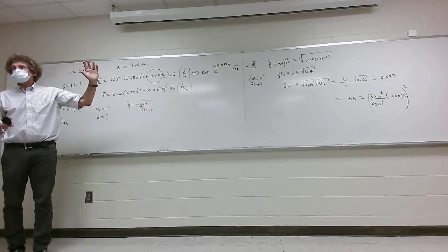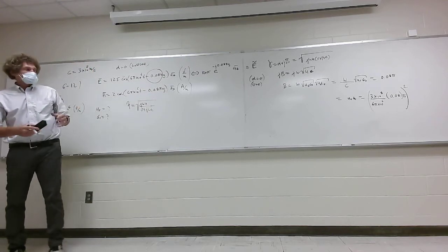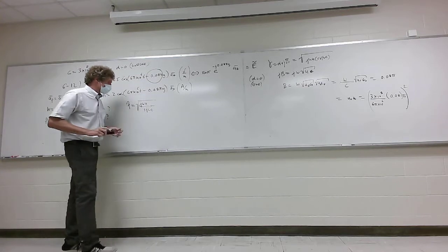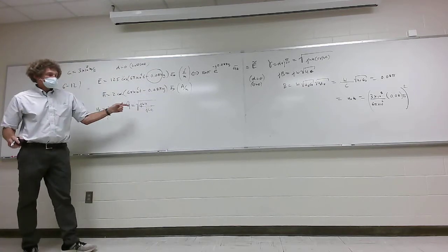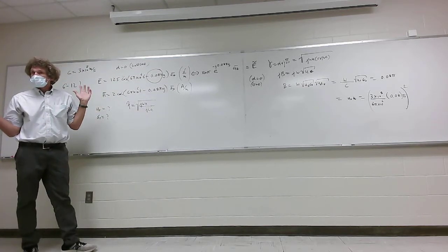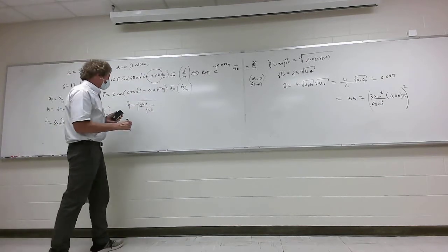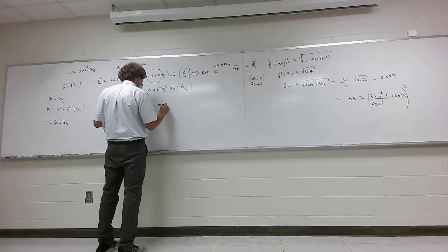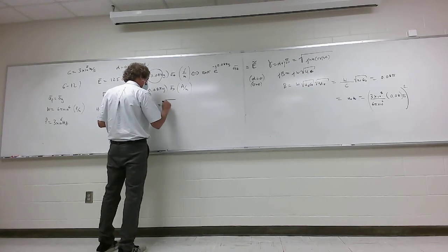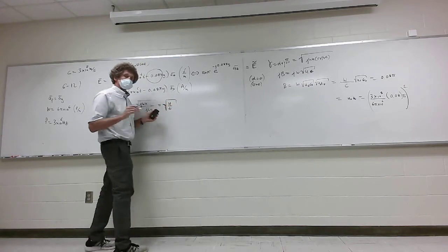Now what did I say here? What did we say about sigma? Its value was? 0. 0, so it goes away. Now take a look at this. You see how the j omegas go away? Everybody? So that means in a lossless environment, your value for eta is just square root of mu over epsilon. I'm going to expand that further.